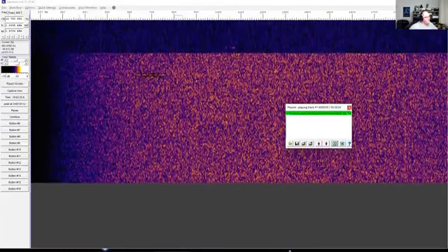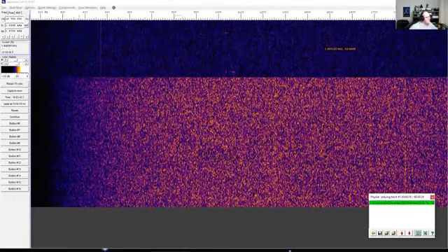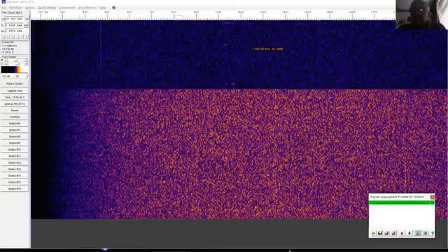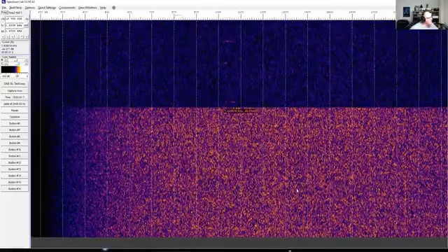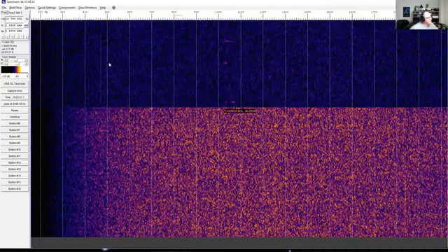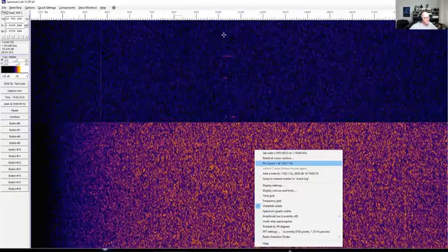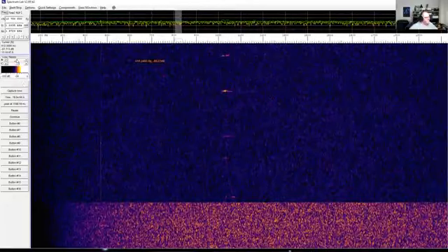And what I'm going to do is show you how to set up this screen. If you notice, there's no waveform at the top. So let's just turn it on. There's a frequency grid, we'll get that off, and we'll turn the waterfall on, and the spectrum graph. Generally I tend to tune it to around a kilohertz, 1000 there, because that's quite easy on the ear. There you go, turn it over a little bit. So we've got those coming in.